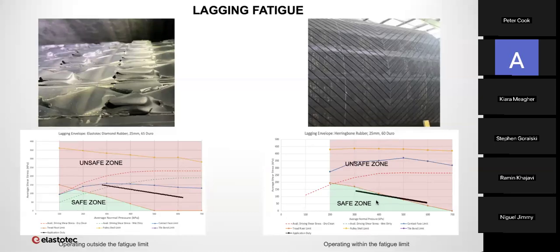This is the graphical printout. You can see here this black operational line has moved down from where it was. It's partially in the green zone. The orange line is the tread root limit, so it's right on the limit. The limit we're using for fatigue life is 5 years. Effectively, this is saying that you're right on the limit, and it may not get to the 5 years.